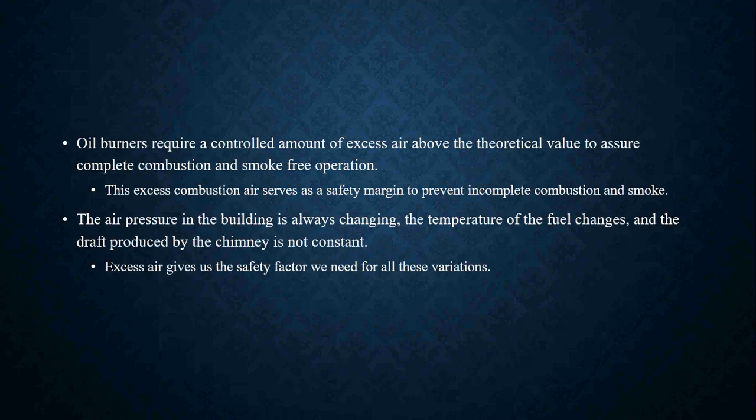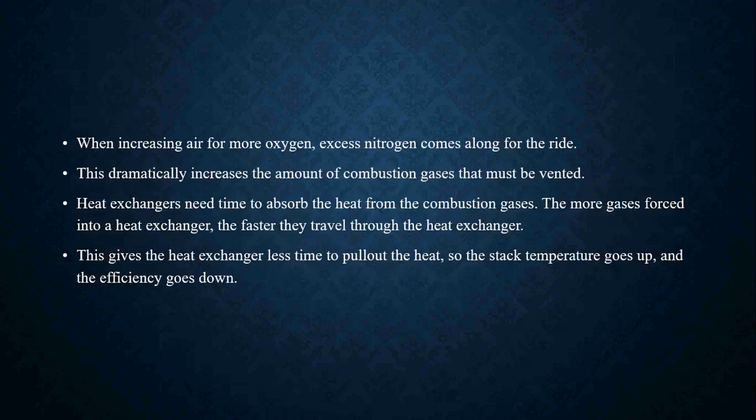If I have enough air in the room or in the space that I'm delivering to that unit, the burner is going to do the rest, especially if it's set up correctly. When we increase air for more oxygen, excess nitrogen comes along for the ride. Okay, this dramatically is going to increase the amount of combustion gases that must be vented.